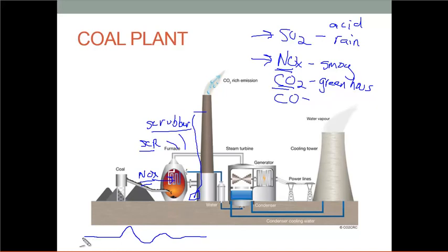But that's one of the things that happens: you talk about the swing rate of the unit. A lot of times these things can go up or down plus or minus, say, 12 megawatts a minute or something like that. 12 megawatts would be pretty high, maybe 5 megawatts a minute. It just depends on the unit and what the unit's capable of doing. But these things can only swing so much. So if you've got 2 units here, maybe you can swing 10 megawatts plus or minus a minute.